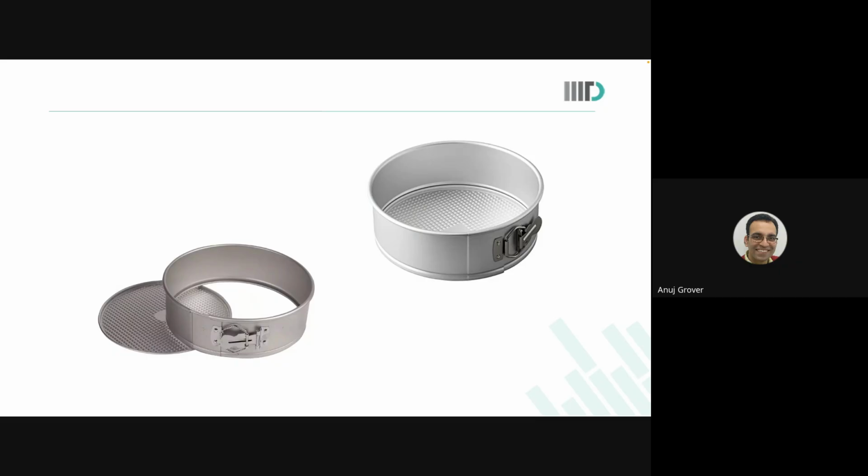The first thing that we need to do is identify what is causing these cracks. Can I eliminate the cracks in the first place? Then we're not even worried about, okay, if I increase the height of my container, the baking time will also increase because the heat has to go into a bigger thing now. So see, there will be other challenges that will come with that kind of a solution. So don't jump to a solution. Look at the process first.